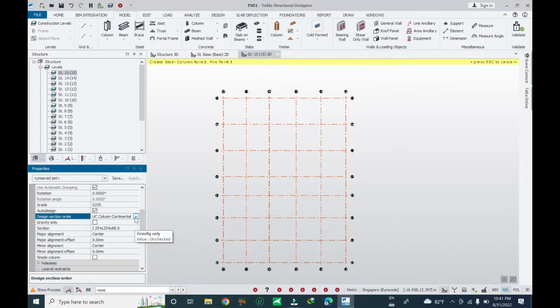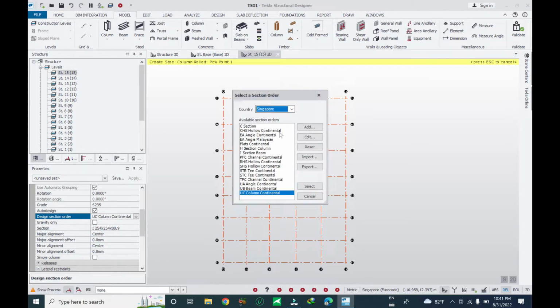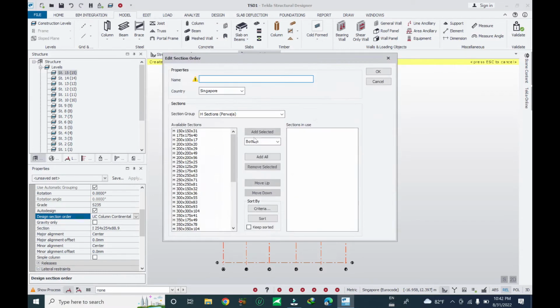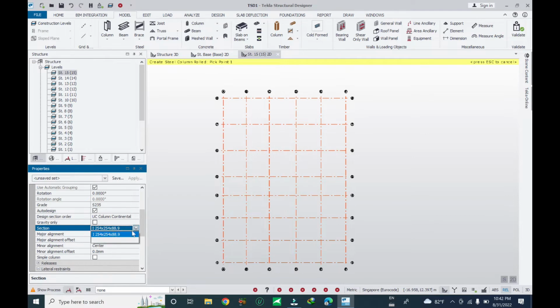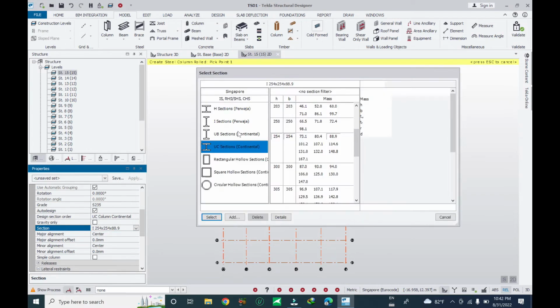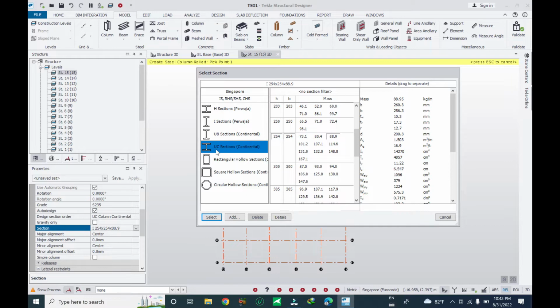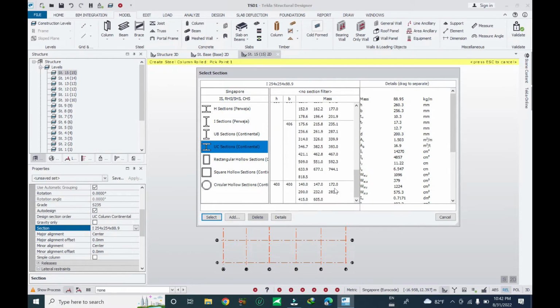And now let me import other section. You can import others for the other section. I beam, H beam. Now let me click H. You can add all and change the name. Now let me use the standard section or the pretty standard UC universal column. Change it to 400. You can use a universal beam for the larger bending. Now let me start from this section.